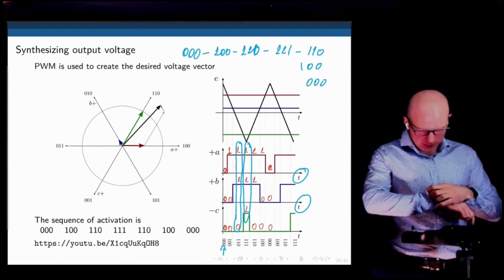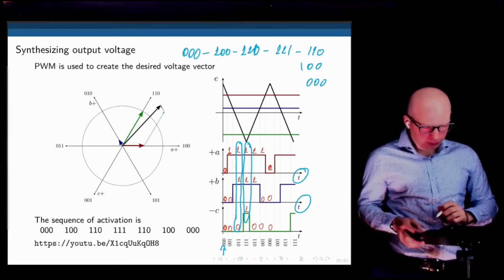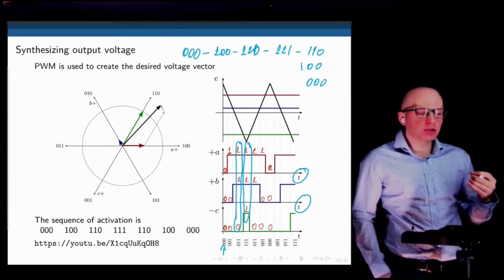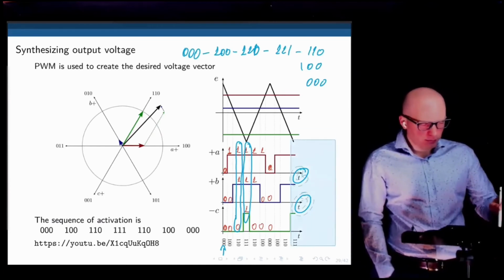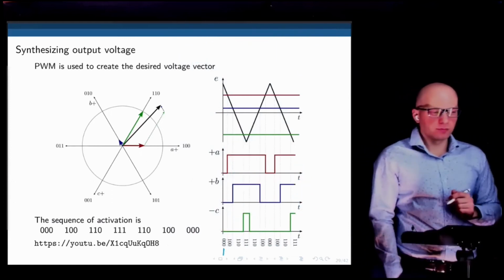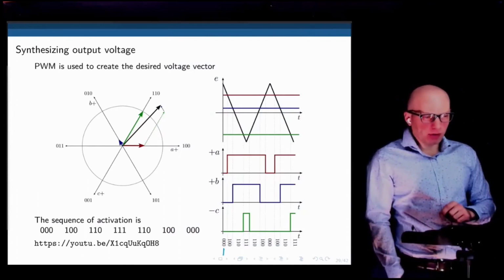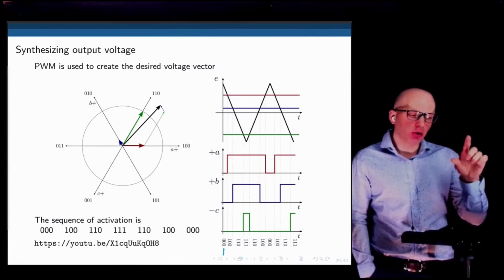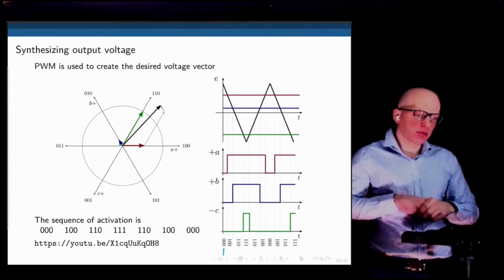Any questions? Yeah, one quick one. What does the circle represent? Does that represent the VS? Yes, this represents the strength of the voltages available for each of these vectors. Okay. So, and then I guess our main vectors, the 1, 1, 0, those can't go more than the available voltage. Not the available voltage per branch of the load, but when we add them up, we go to VS. Okay.